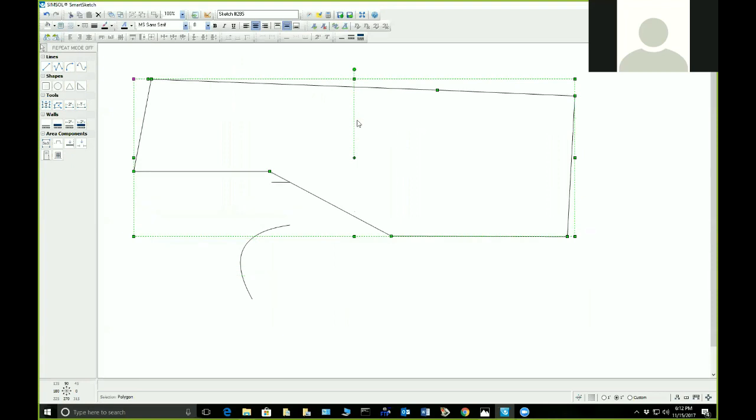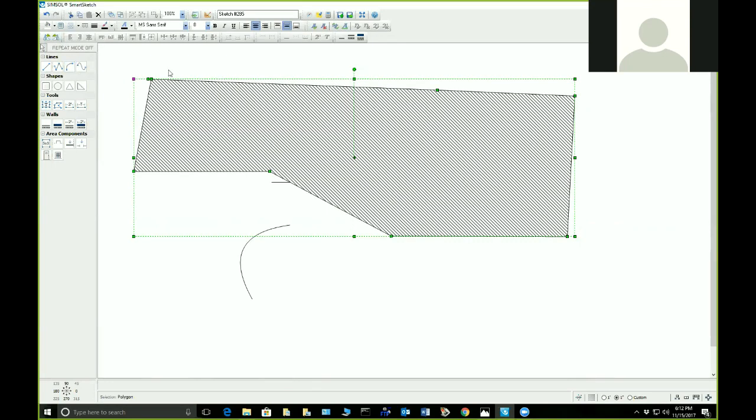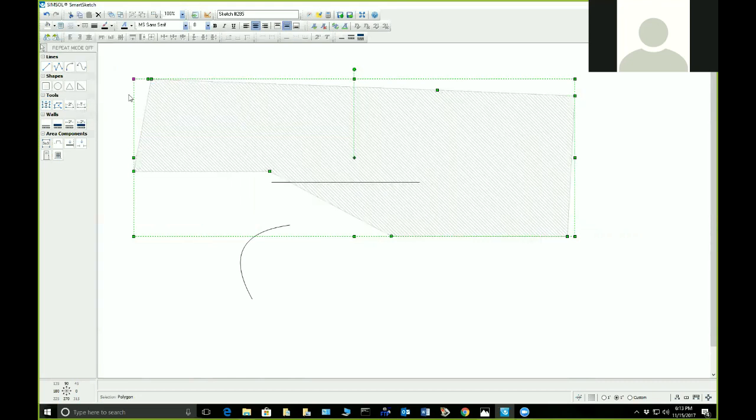So you can see that I have something here. If I want to put some color in here, it makes it kind of nice. Since I have an enclosure from the polyline, let's see if we can put a pattern in, which I can do. And then as you can see how I'm using my edit toolbars, I can pick the line style. But also what I can do is do the pattern as well as the transparency. So that works out really well. Watch this. If you need to lighten that up a little bit, you can do that. So you can use the transparency along with the pattern on here. Line style, if I need to make it thick or thin, I can do so, and also the line color.